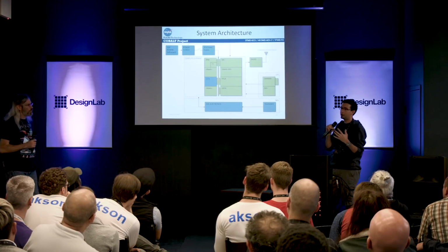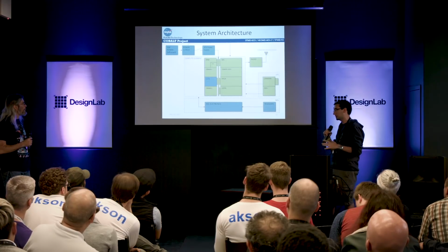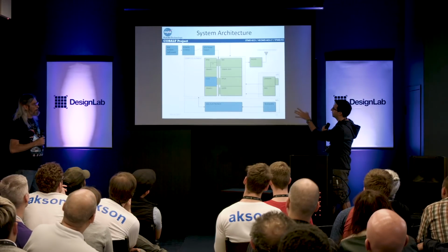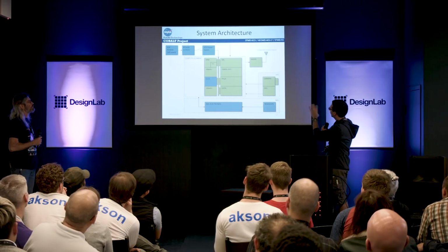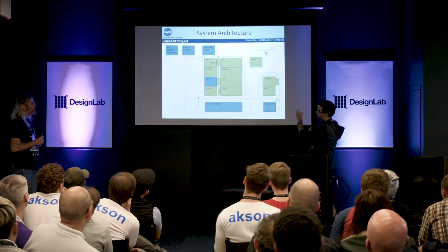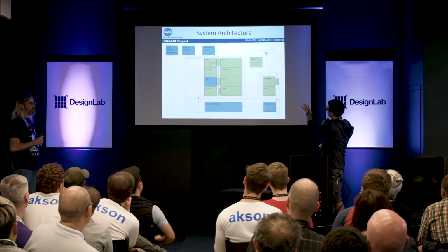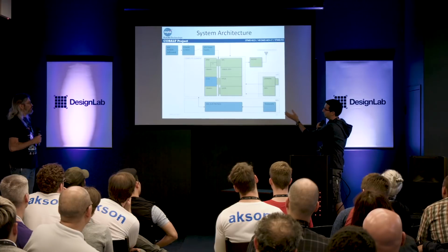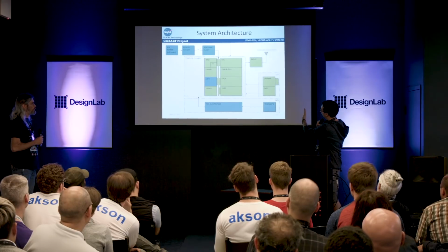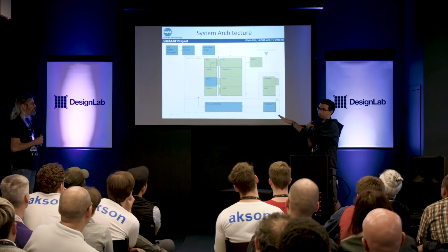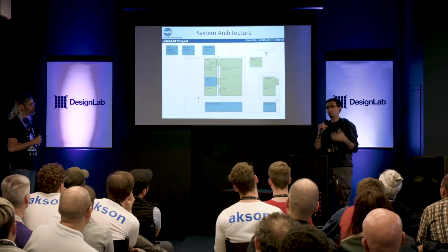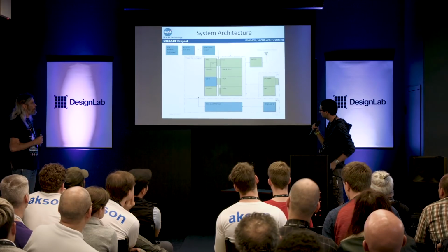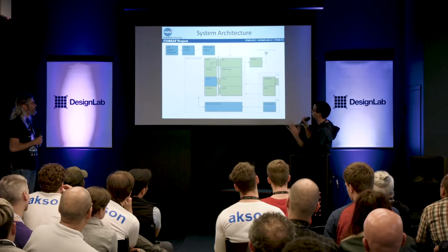So we had a power condo that had batteries, a battery monitoring system, a bunch of power harnessing that supplied power to our three main subsystems, the compute element, our lander vision system, and then the LiDAR. So the lander vision system consisted of a camera and an IMU. The NDL, the navigation Doppler LiDAR, the LiDAR itself has a telescope and then an electronics box with the actual lasers and sensors and whatnot, and that provides us velocity and position. So all that information is fed into our computer.